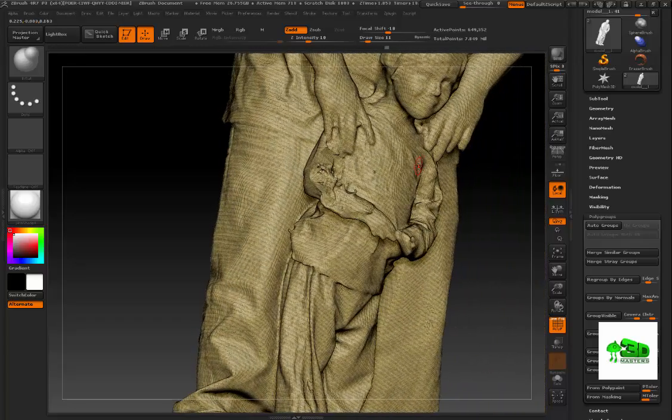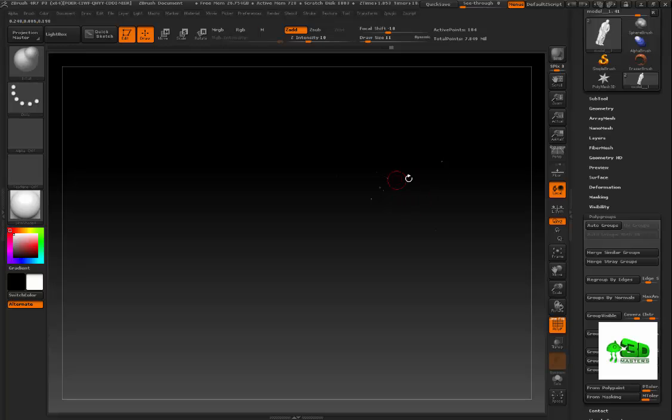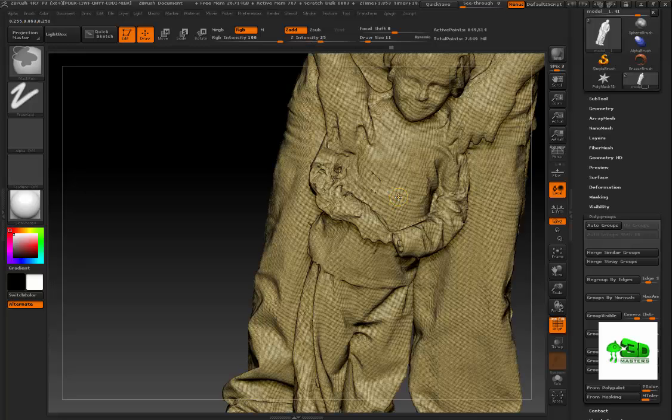Yeah, what I did there is I hold down Control, Shift, Alt, and then you select the model, and you see what artifacts are left there. So I'm going to do Control, Shift, Alt, and select it again. Control, Alt, Shift, and then left click, and then you see the ones that are gone. I'm going to delete those little artifacts that were hanging around the model.